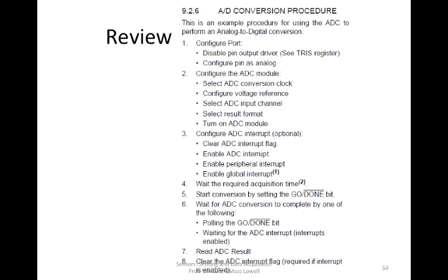All right, to summarize, to perform this ADC conversion procedure, you need to follow the following steps. The very first one, you need to configure the port properly. You need to set the pin as an input pin, and you want to set it as analog. After that, you will need to configure the ADC module.